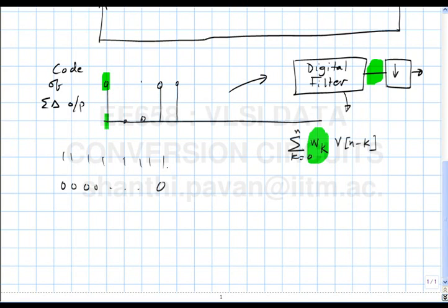Then what happens if you take a step-like quantized waveform and pass it through a low pass filter? All the steps get smoothed out, which is equivalent to saying all the high frequency components of the input get filtered off, correct? Which means that if you look at only the energy within the signal band, there is signal and this.